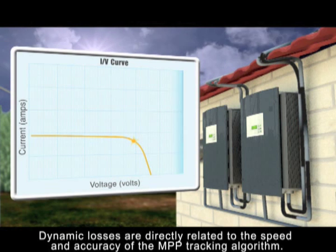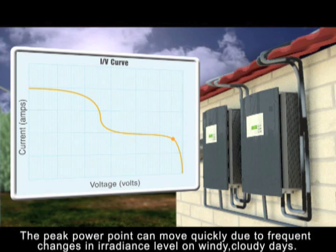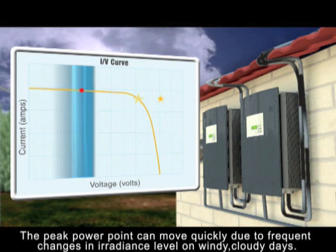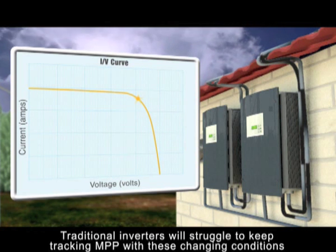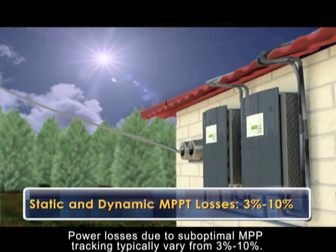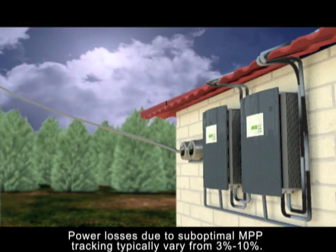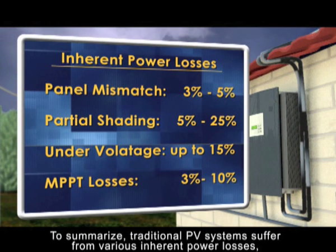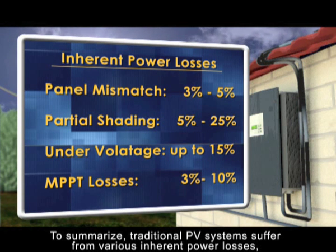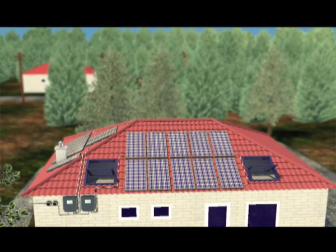Dynamic losses are directly related to the speed and the accuracy of the MPP tracking algorithm. The peak power point can move quickly due to frequent changes in irradiance levels on windy, cloudy days. Traditional inverters will struggle to keep tracking MPP with these changing conditions. Power losses due to suboptimal MPP tracking typically vary between 3 and 10%. To summarize, traditional PV systems suffer from various inherent power losses stemming from a centralized topology.